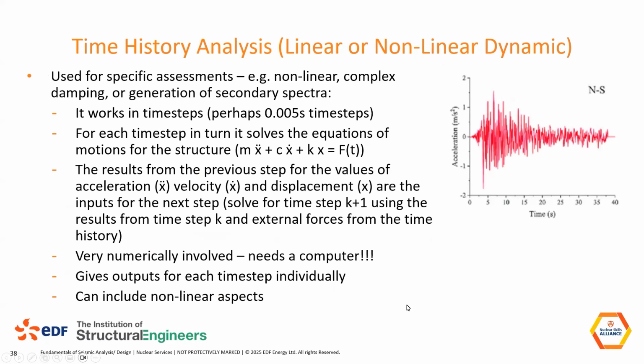Time history is a more complex, or at least a more computationally intensive method. Essentially, you resolve this input and the design of the structure as a series of individual time steps where you solve this equation we saw before, so the mass times acceleration, damping times velocity, and stiffness times displacement for each time step.